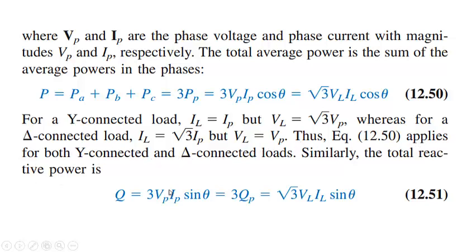Similarly, total reactive power will be equal to 3 times Vp Ip sin of theta, which is equal to 3 Qp, which is equal to root 3 times VL IL sin of theta. These two are very important relations you need to remember.